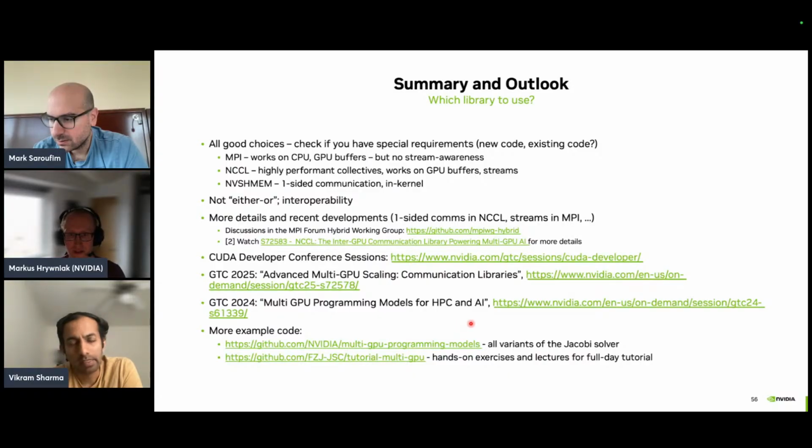I think there is a clarification question. Do we need, for any NVSHMEM collective launch, the cooperative group to be made available, and then you should be launching? So should we use cooperative groups or not? You can use them. What I didn't show is the launch for the actual kernel. Because if you want to do in-kernel synchronization, you need to make sure that all the threads that need to be synchronized are also scheduled right now on the GPU. So there are some more details in the NVSHMEM documentation, which, if you want to use it, you will figure out, but it's just important to point out that this is another kind of cooperation before you actually get to the thread groups. Yeah.